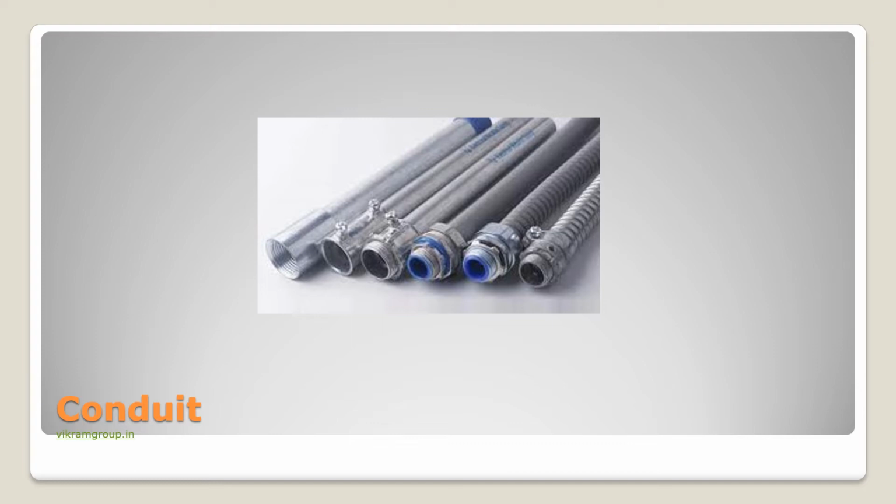To the far right, you see two different types of flexible conduit. Flexible conduit can either be sealed, which is the gray one that has the blue end on it. So that could be gas tight or watertight, and could be used in a moist environment or a gaseous environment where you might have an explosive vapor. The one on the right isn't sealed. It just provides some flexibility.